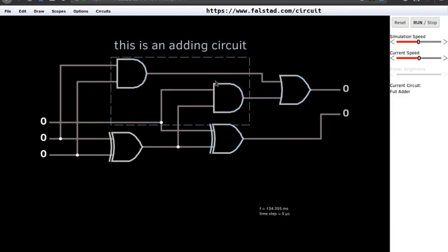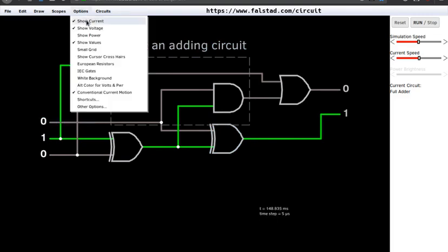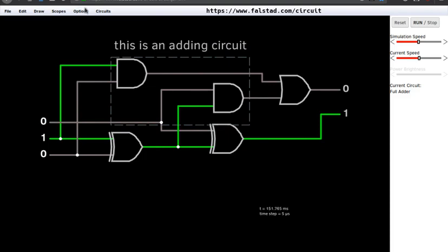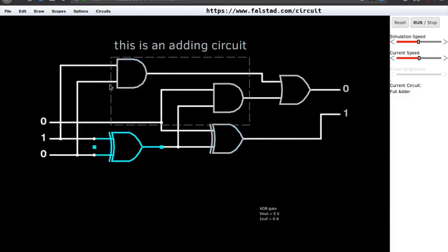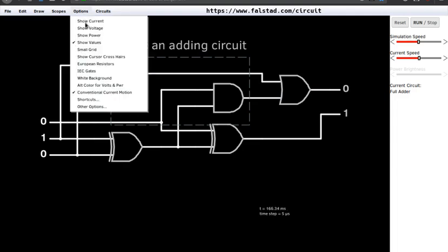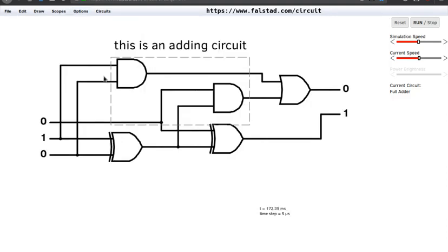It's more useful when you are doing a schematic to show other people. So if you are doing a schematic, there's a lot going on which isn't very useful. All the coloring and the yellow dots to show the current. So you can go to options and you can hide the current if there's any, and you can also hide voltage, and it will make this white on black schematic. To make it with a white background, you can go to here, white background, and the schematic will be dark.